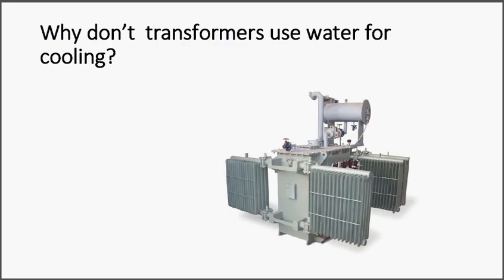Okay, right, let's go further. We've got transformers, and you can see a massive transformer here. Anyway, you can see those grills on either side of the transformer, and they are cooling grills. So that's meant for cooling. You've got some fins, the air blown through those fins cools the oil down. And over here we've got an expansion tank as well. If the oil heats up, it expands a little bit, so it moves in there.